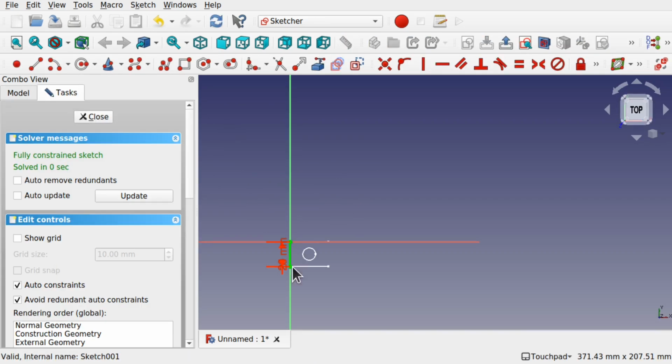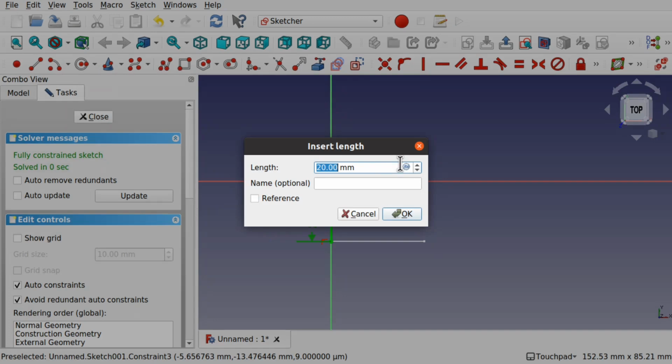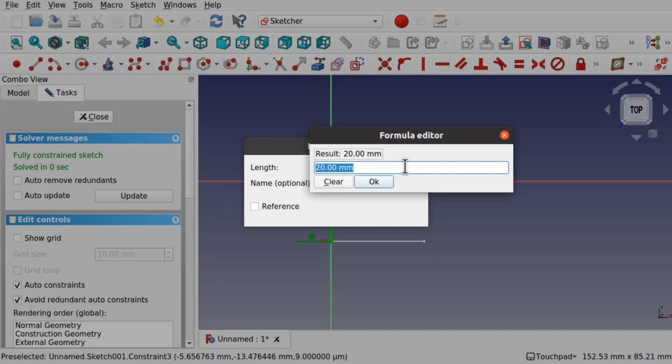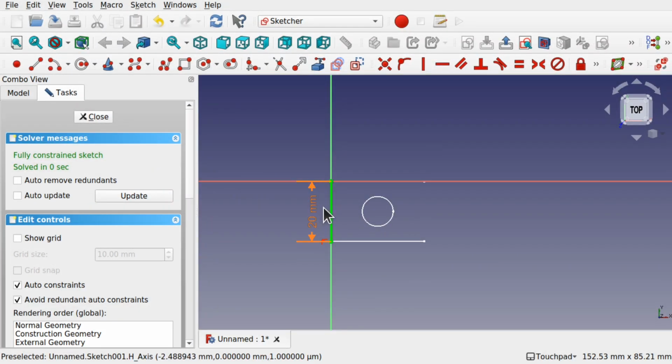Let's double click that sketch, come in and double click this height here, go into the formula, and this was on the repeat sketch. Let's click it, dot constraints. Now I'm going to press the down key there and hit enter. So we've got the constraints there, and dot height length, 20 millimeters. Hit OK and hit OK again. So that's fixed now, so if anything changes, that will change as well.